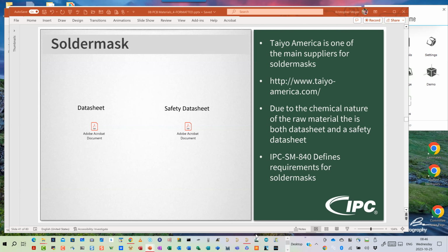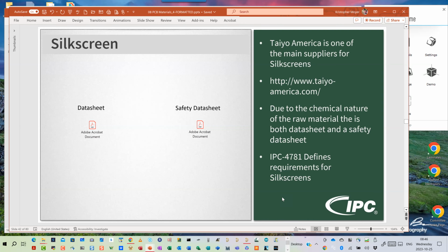Additionally, there's going to be a minimum, what we call a sliver width, for the solder mask as well as the silkscreen, which we're going to talk about next. There is a minimum line width that the fabricator can actually print a strip of the solder mask in. So if it gets too small, there's some things we can do about that. Remind me, if not today, next week during manufacturing, and we'll talk about that some more. Okay? So we talked solder mask.